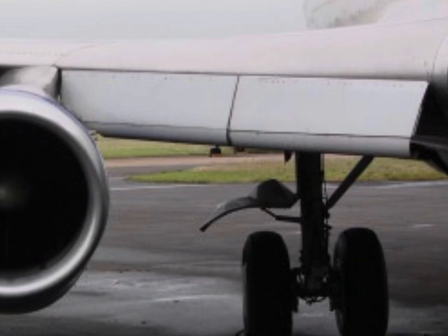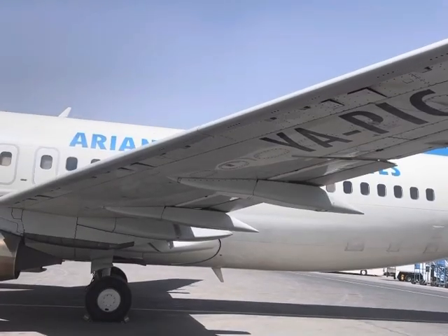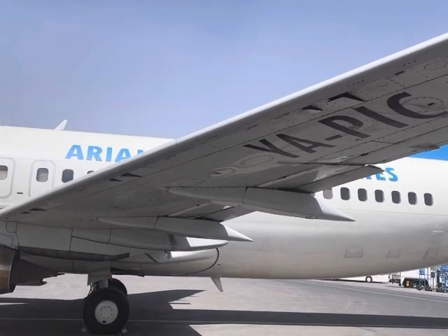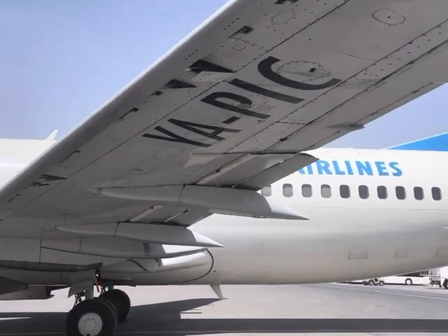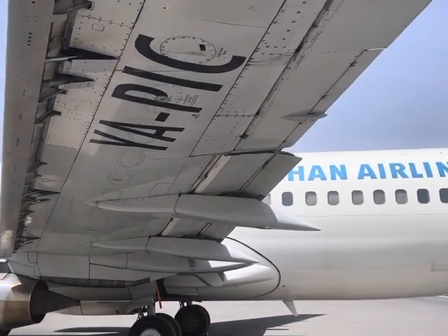Then in the leading edge slats, we have three positions. The first position is the retract position, then we have the extend position, then we have the full extend position. And because the leading edge slats are in the portion of the leading edge where the shape of the wing is thin, besides that curvature problem that we talked about before, there is possibility of ice buildup on the leading edge slats. So we have an anti-ice system to prevent this.